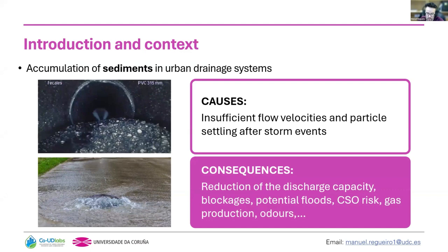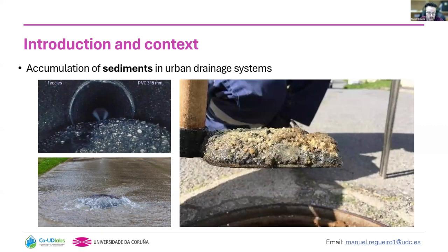These sediments may produce blockages, and in some cases even floods, combined sewer overflows, and other problems like gas production, bad odors, and so on. So when we are talking about sediments or measuring sediments, we talk about sediment depth, and how to measure this variable.